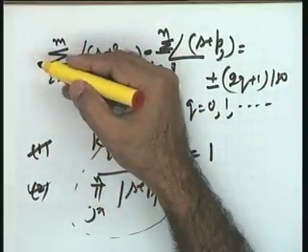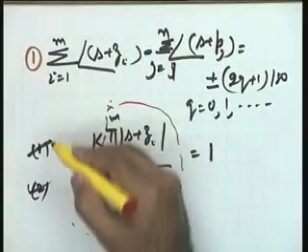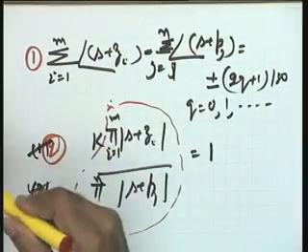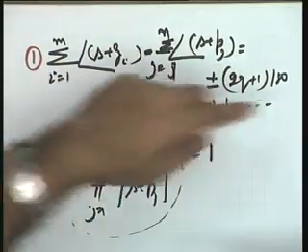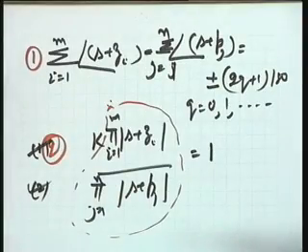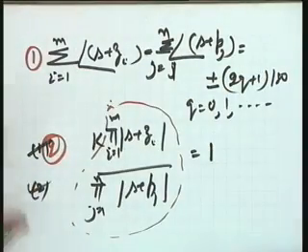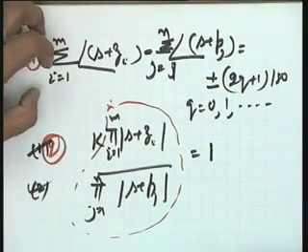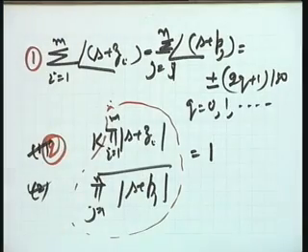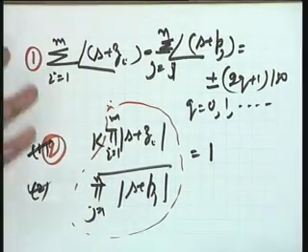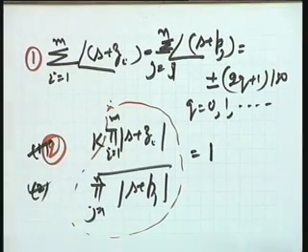But a root locus point will mean that both conditions 1 and 2 must be satisfied. So I proceed like this. First I look at the angle condition. You see, every point in the S plane does not satisfy the angle condition, that you can check. So I scan through the entire S plane and locate the points which satisfy the angle condition, join all those points, and that gives me the root locus plot, because the magnitude condition will definitely be satisfied for some value of k.